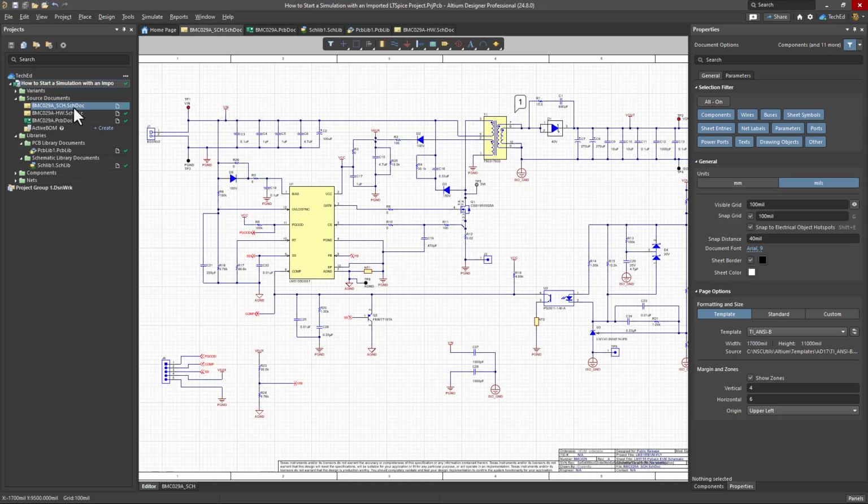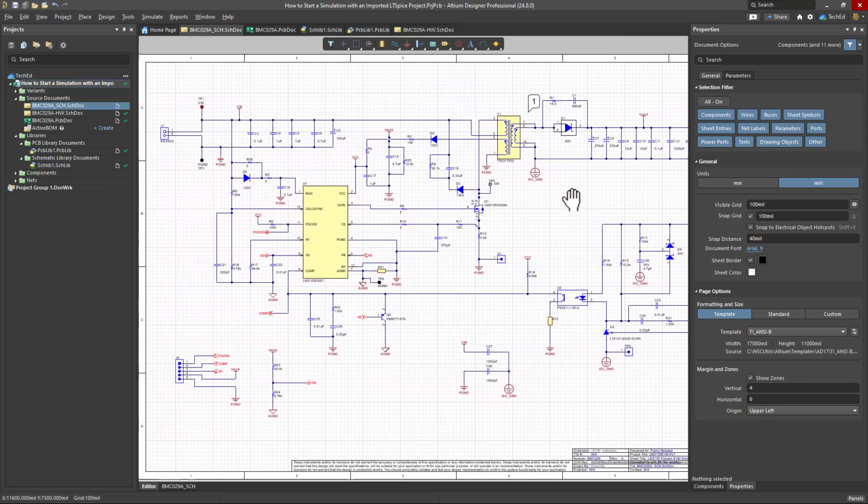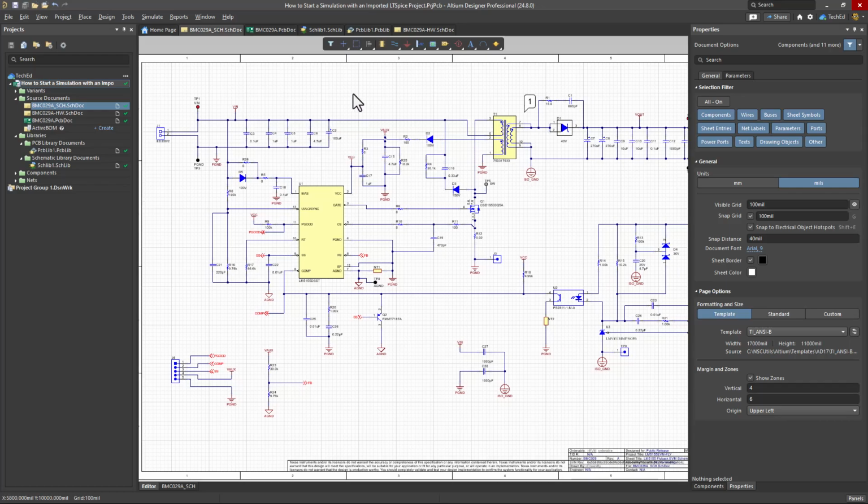First, you have a schematic doc file. I'm looking at a project right now where we have our schematic doc file. This is to represent the schematic. Each page of your schematic in Altium is in a separate file. You may see in other ECAD software where one file captures all the schematic pages. Well, no, each schematic page has one file.